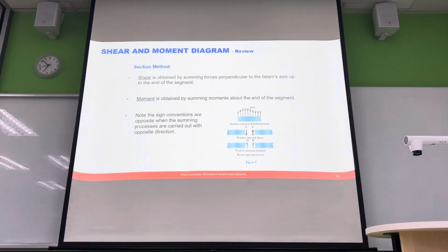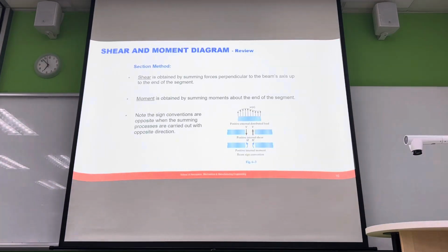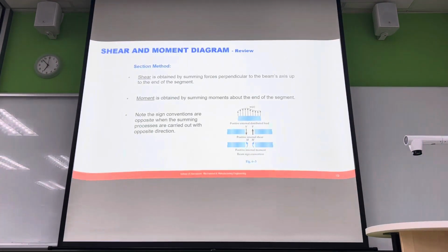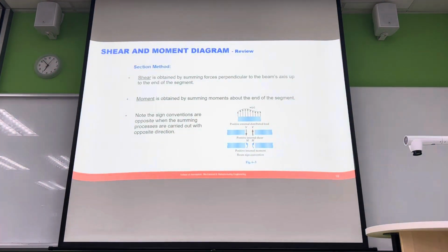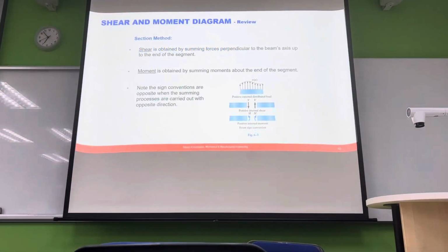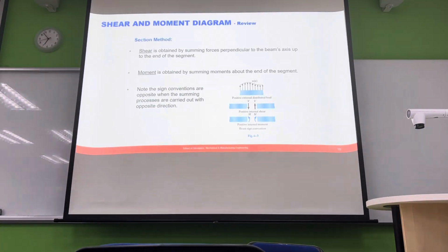So that means, on the whole, that for this expertly manufactured beam that I have in front of me to be in equilibrium, the sum of forces and the sum of moments on that beam need to be equal to 0. And that's not true just for the whole beam itself, but no matter how I cut that beam up, no matter if I look at this portion over here, or look at this portion over here, if I cut the strip off the middle, if I go and break it up,